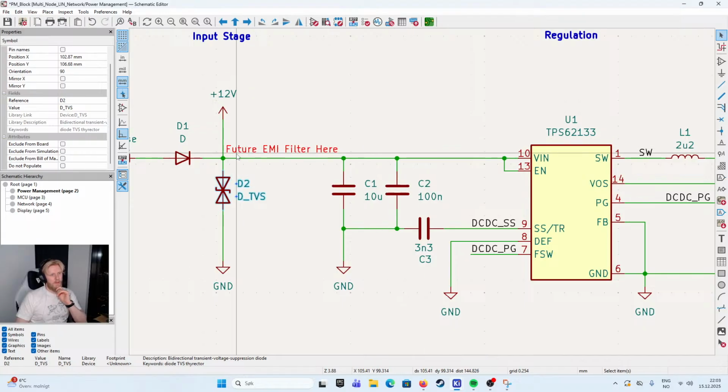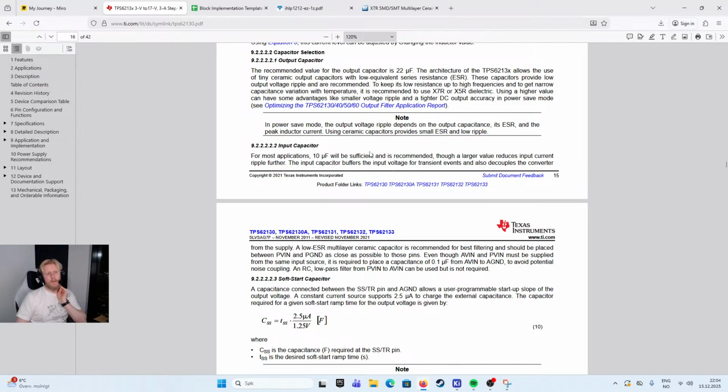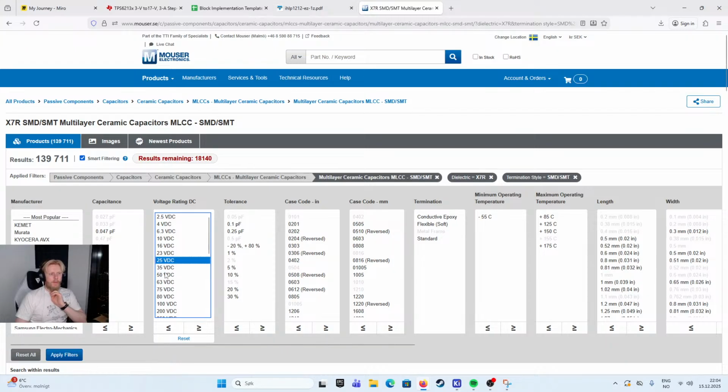I think maybe it's best that we select 25 on these, so they're above what the input of this DC-DC. Because if it really was 16 max here, then I wouldn't have to select a DC-DC higher. Right, I could also select it lower. Maybe. Let's go with 25.